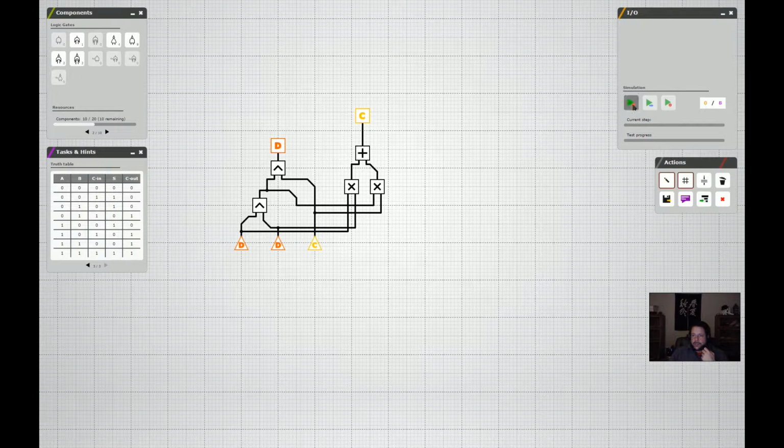Yeah, well, let's see if it works. I think this is the circuit that I built before, but we'll double check. Okay, when everything is 0, both outputs are 0. There's 8 tests here. When carry in is a 1, sum is a 1. Okay, so we got that passing up. It doesn't get through the AND gate because the other condition here isn't met. I don't know if any of that made sense, by the way. I know it was a lot of crazy talk. All right, so here they're not matched, so it goes through that XOR. These aren't matched, so it goes through that XOR, and it doesn't make it up here into the carry. So we just get the output on sum.